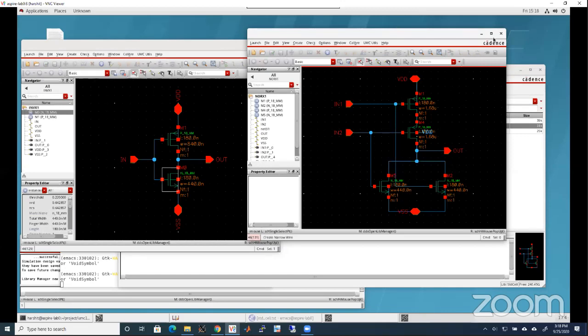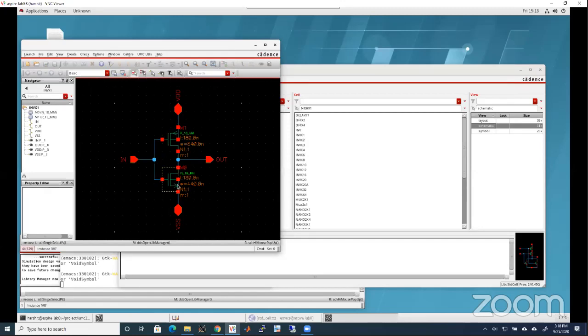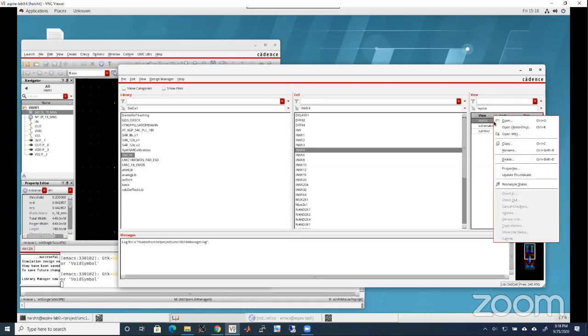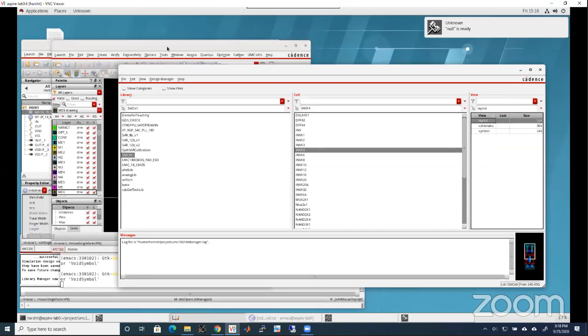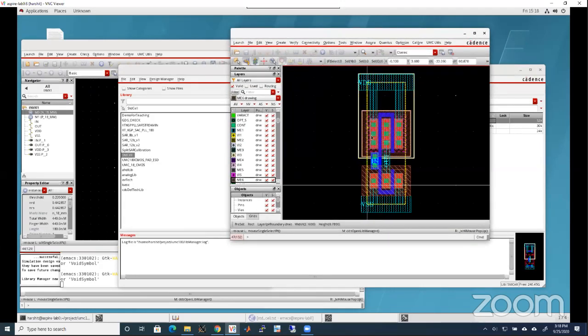Okay. So anyway, let's assume that we have sized it correctly. Now, what does this sizing strategy say? That the NMOS is half the size of the PMOS. And the layout of the standard cell is defined by the number of tracks. What is the meaning of number of tracks? How many metal lines can be routed between the VDD and ground line.